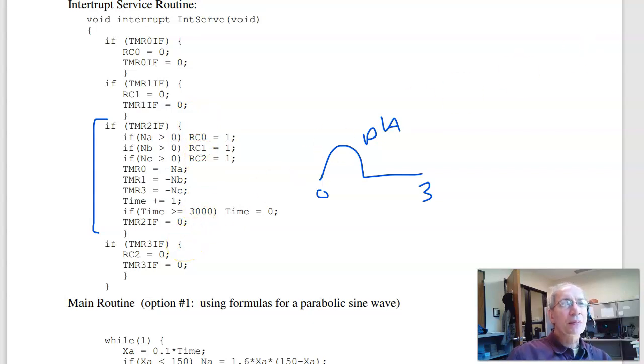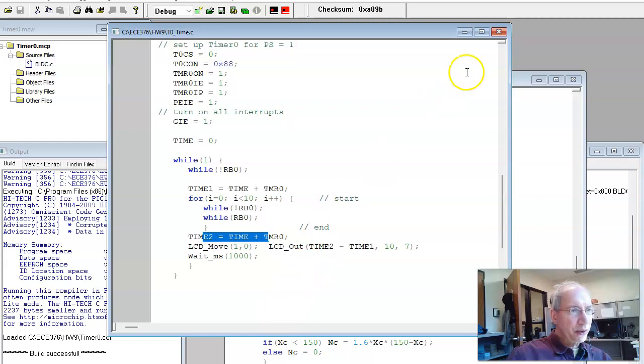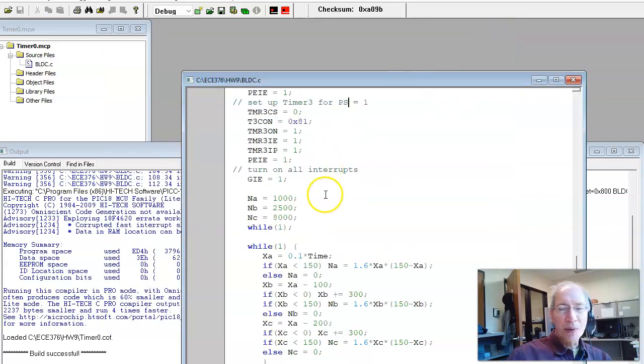To check that out, let's write a test code. That's typical in programming. I want to write a test routine. If I set the pulse width to 1,000, 2,500, 8,000, where 1 millisecond is 10,000 clocks, if I set these, what I should see is 10%, 25%, 80%.